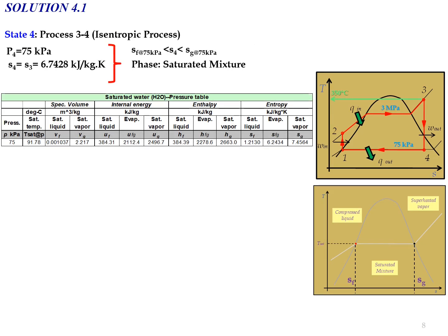For state number 4, in terms of enthalpy, we need to manipulate the entropy formula that we learned in Thermodynamics 1. Just rearrange the equation. From the equation, we can obtain the quality of steam at state number 4: X4 equal to S4 minus SF at 75 kilopascal divided by SFG at 75 kilopascal. S4 we already obtained, and SF and SFG we can determine from the saturated water table at 75 kilopascal.